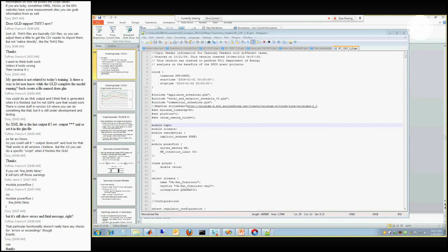Most of the runs of triplex cabling are in the order of like 10 to 50 feet. You might get a volt drop across them. The standard utility idea is across the transformer, the cable, and the meter itself, you have about a 3-volt drop. So not having that in there is not the end of the world. Okay. Triplex cabling hasn't been in those models for 50 years, so.